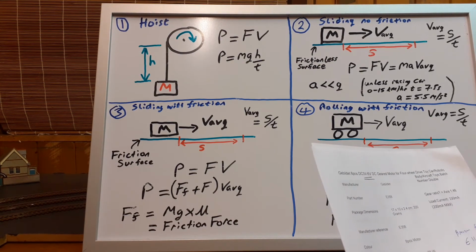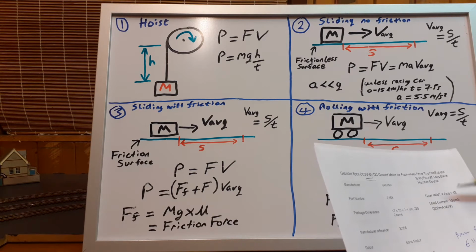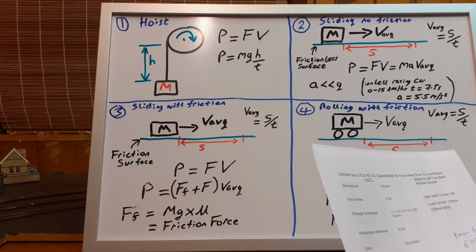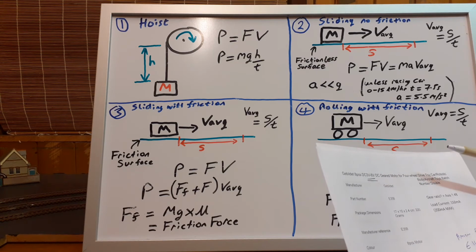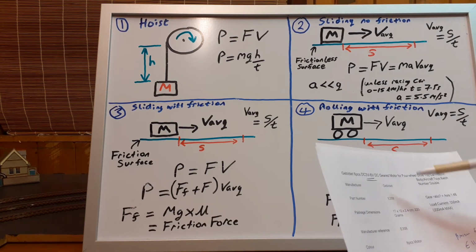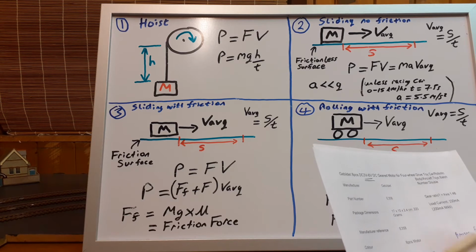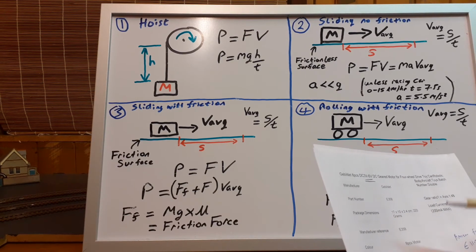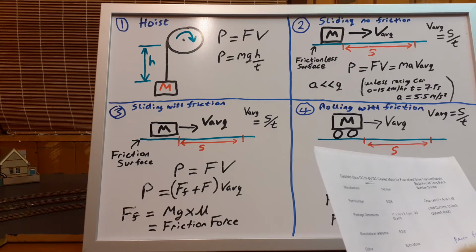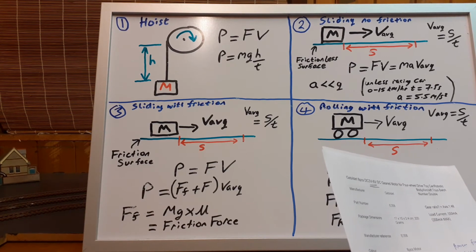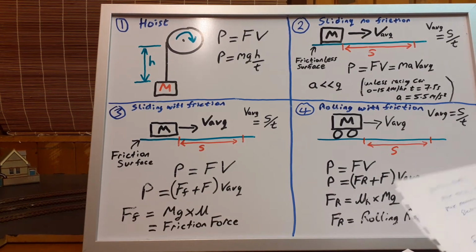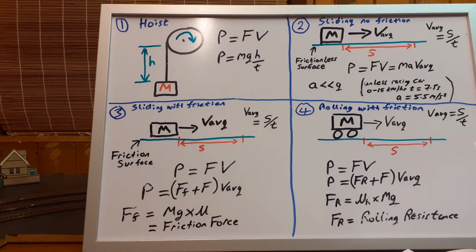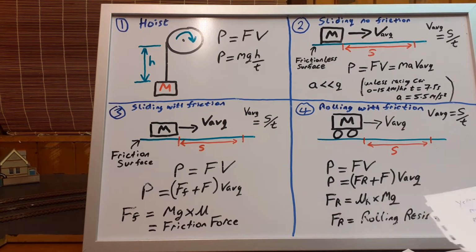But even if it's running at 6 volts, and it's got the max current of 0.2 amps, with 6 by 0.2 it doesn't come anywhere close to 75. I just think this is completely wrong. What's 6 by 0.2? I have my calculator here, but it's nowhere near that. So this is not an accurate spec. Now, what is interesting about this is the max power I found I got out of it was about 0.076 watts. So maybe there's some kind of error by 100 there, or 1,000 or something like that.